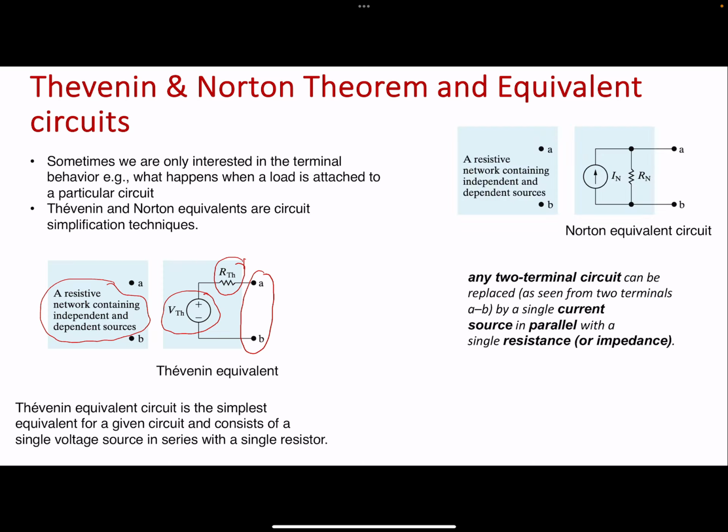Similarly, on the other end, the Norton equivalent circuit provides a similar circuit, but you want to have a different representation, where again you find the equivalent resistance of those circuits, where R Thevenin is here, RN is here. The process of finding RN and R Thevenin is exactly the same.